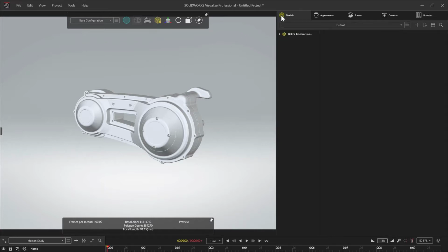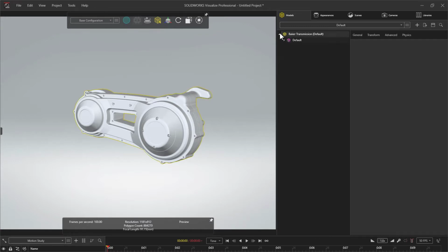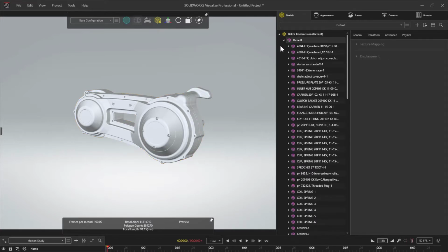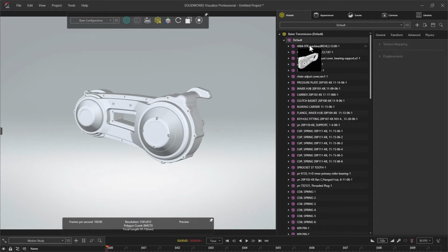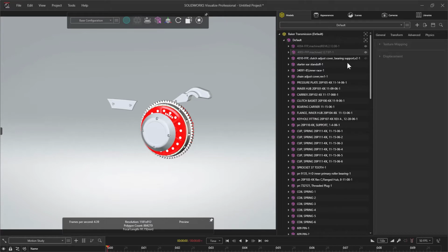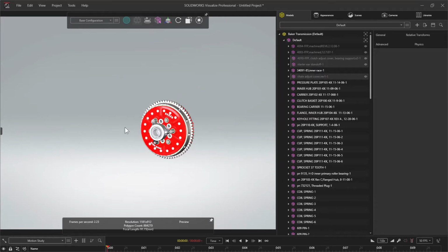So let's take a look at the Models tab now that we've imported this with the advanced method. We can see the model, which has the yellow cube. We've got our first group, which is indicated by a purple cube, and then inside that are many more groups, whereas last time they were named after the materials and they were parts. This time they're groups and they're named after the parts and subassemblies. So you can again see previews here. We can again change to a selection mode that uses groups. So if I click here, you'll see it cross-highlight. We can again hide them the same exact way we did prior, and we can continue and hide from the screen the same way.